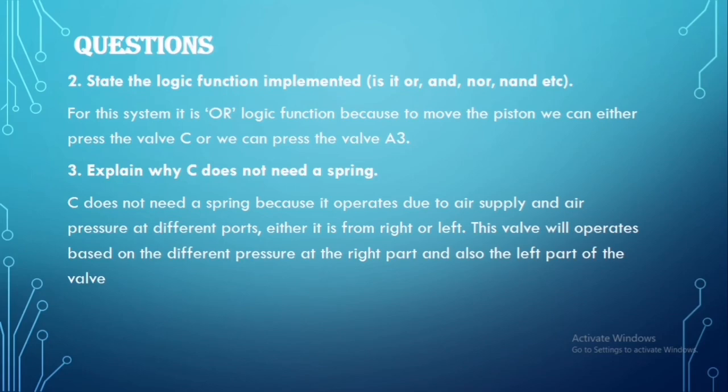The last question is explain why C does not need a spring. C does not need a spring because it operates due to air supply and pressure at different ports, either from right or left. This valve will operate based on the different pressure at the right part and also the left part of the valve. That's all from me.